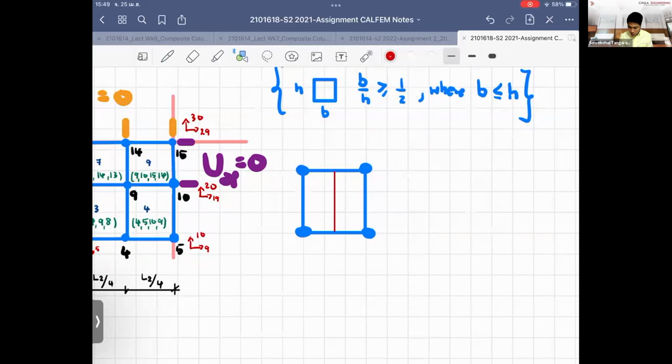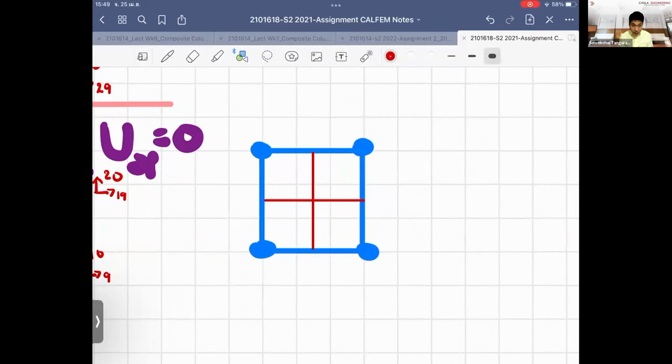So they divide it into 4. The stress value that you can obtain from the finite element package, which is derived from the displacement fields, gives you the information of the stress at the Gauss point. It is located at 1 over the square root of 3 from the edge, on each of the edges.